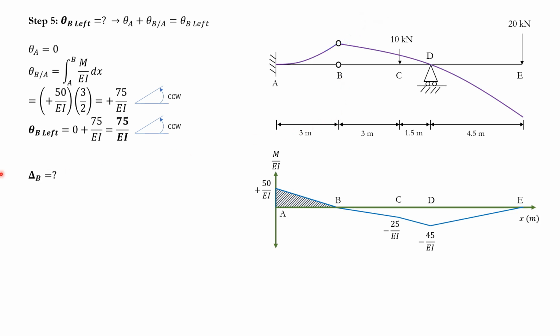Well, in this case, I know, as we talked about before, this is TB with respect to A, right? So this is TB with respect to A. Why is that again? Because again, you draw a slope from A, deviation is measured at B. Slope from A, deviation measured at B. So, in other words, we say that delta B is equal to TB with respect to A, of course. And according to the second theorem, that's just the moment of this area about point B, right? About point B, right there, okay?